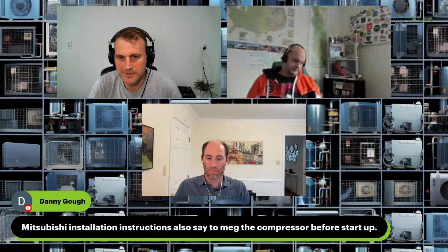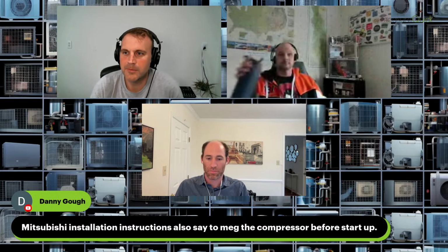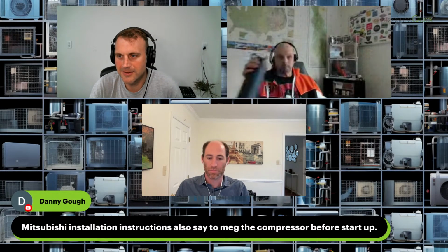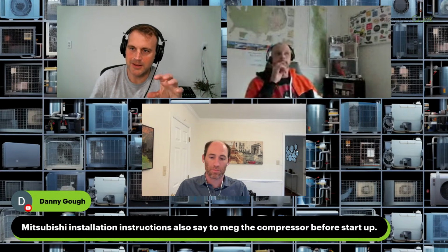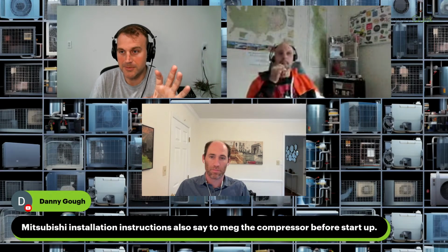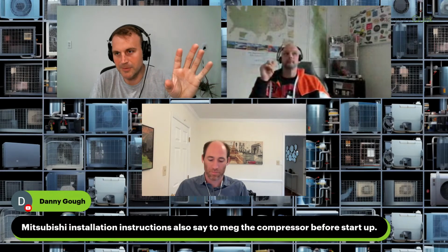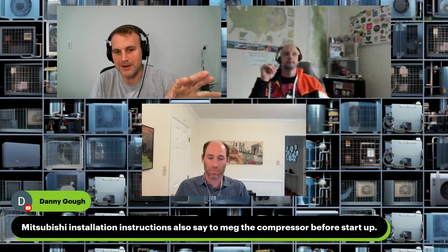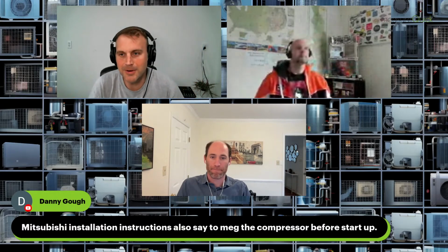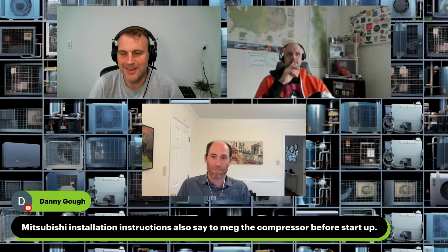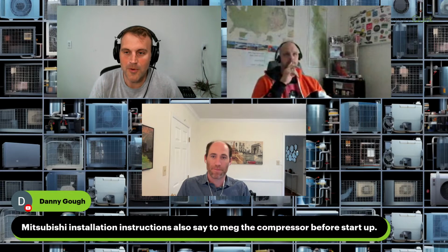Yeah. This was my first design with their piece of equipment. Ben kind of was shooting me data, and at that point, I felt comfortable because I'm looking at the published sensible heat ratio from the submittal, the sensible heat factor of the coil, and the sensible heat ratio of the house. And I'm like, well, we've got a good number, right? We know this thing can achieve what we're trying to do. How far can I optimize that? That's where I'd like to dig in deeper and know more.